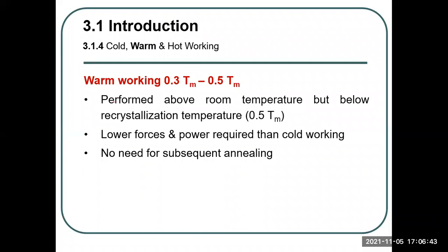And then warm work is something quite weird in between, just above room temperature but below 0.5 of the melting temperature. Obviously, because you increase the temperature, the force will be lower and the power will be lower. And there's no need for annealing.